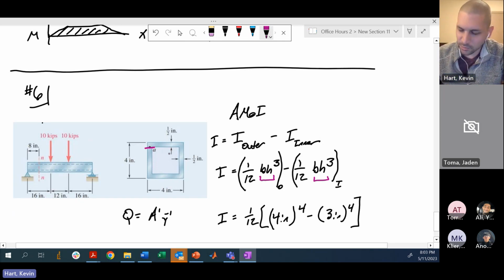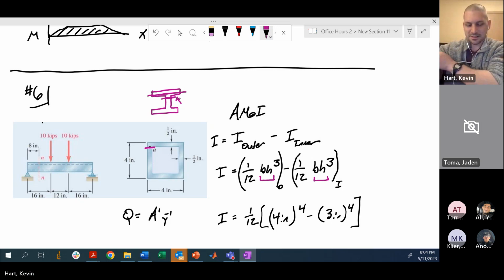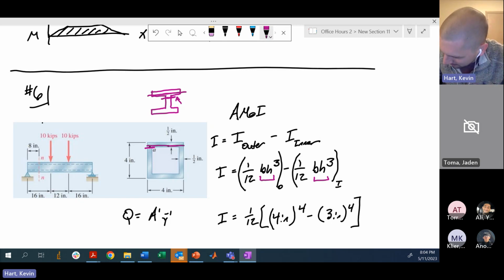Yeah. And we sort of saw this with I-beams as well, where when you go from a skinny part to a fat part, we know that we have much more shear in the skinny part. So when you're right on this boundary between the skinny part and the fat part, you go with the lower value, because we have this smaller thickness that needs to bear the brunt of all the stress. So instead of picking the full width of this box beam, we're going to look at this little slice.